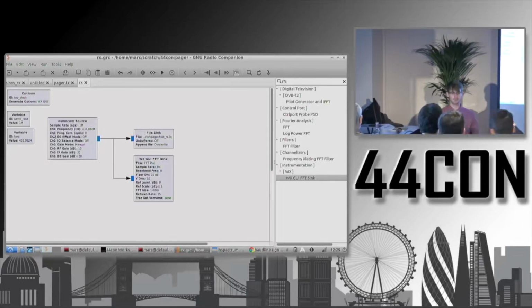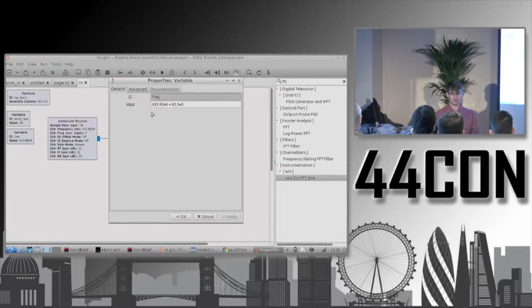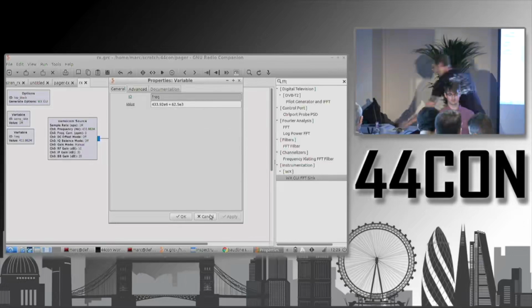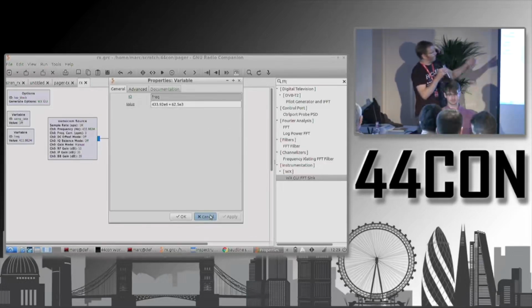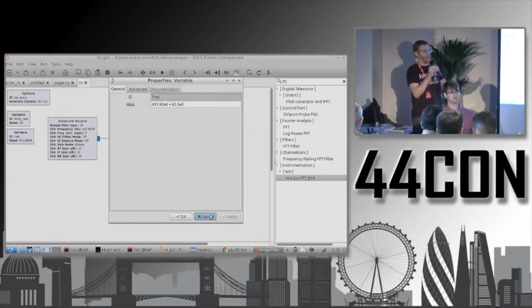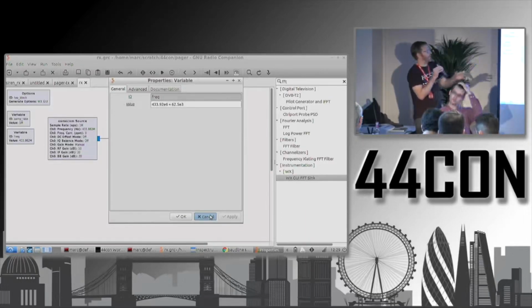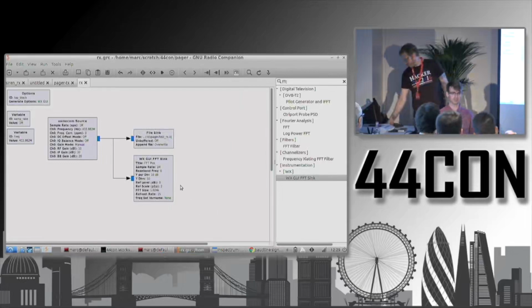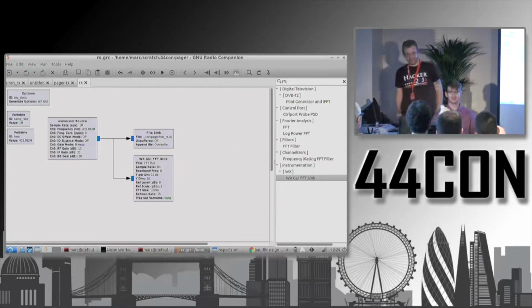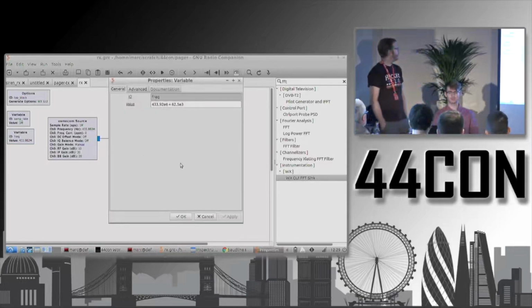Yeah, so just one moment. And the frequency is 433.92e6 plus 62.5e3. The reason we have that offset there is that the documentation indicated 433.92 megahertz, but then we observed that the actual signal was 62.5 kilohertz above that 433.92. So we're writing it that way to make it clear that it's what we had documented plus what we actually observed. Sorry, and then just go back to the variable frequency function. Yeah, sure.